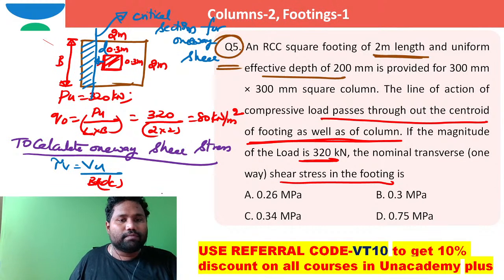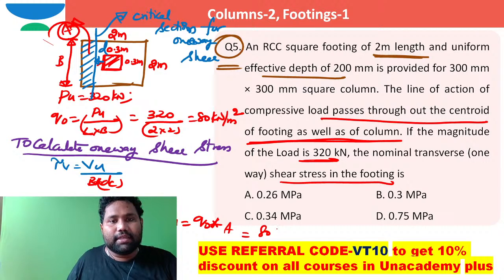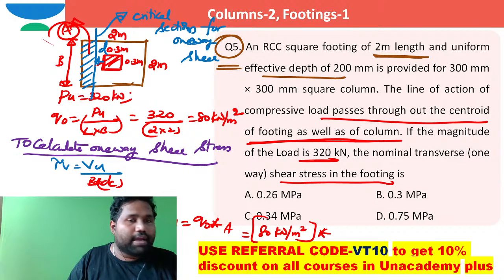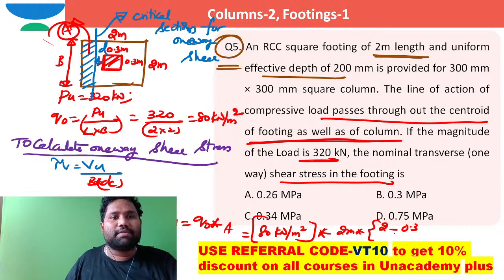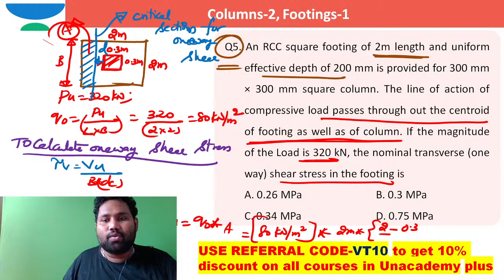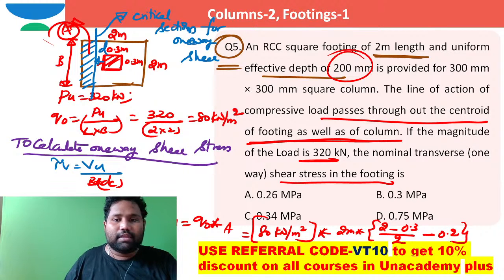So how can you work out this Vu? Vu is equal to Q naught multiplied by this hatched portion area A. Q naught is 80 kilonewton per meter square, into area A. What is this area A? You can write it as 2 meter multiplied by (2 minus 0.3) by 2 minus the effective depth. The effective depth is 200 millimeter, so minus 0.2. If I do this, the answer for Vu you are going to end up with is 104 kilonewton.